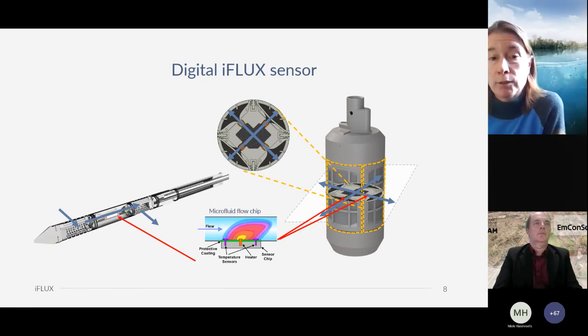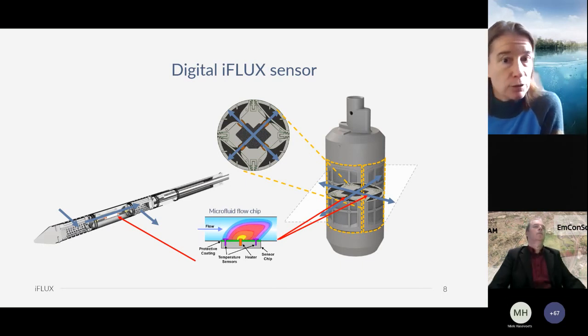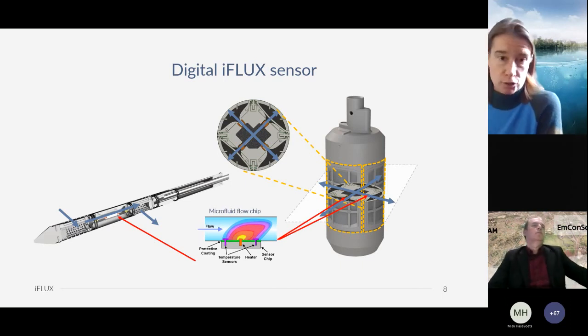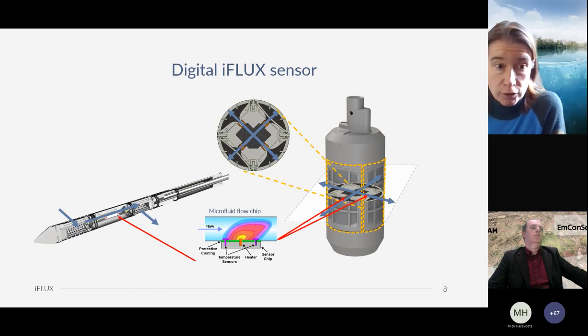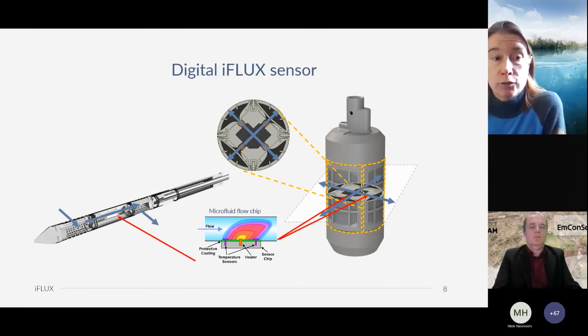We have a probe for measuring horizontal flux, where 2 sensors are built in perpendicular to each other. Based on the vector sum, the groundwater flow velocity and direction can be determined. Another probe is developed for measuring the vertical flow, and here 1 sensor is included, which can measure upwards and downwards flow of water.